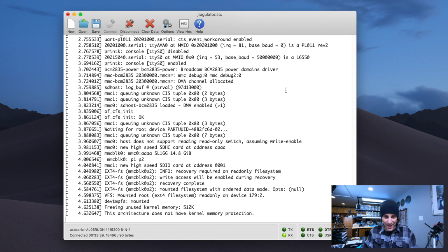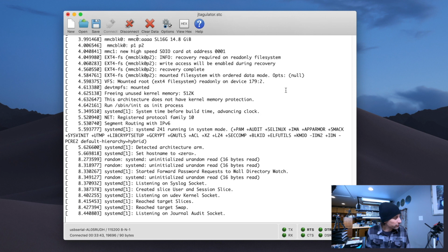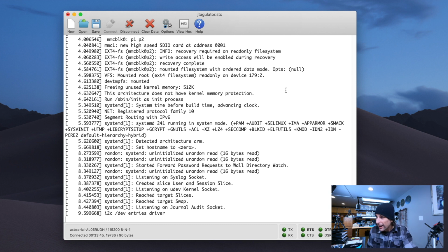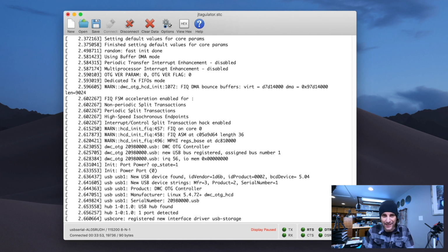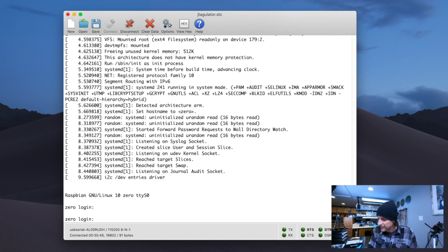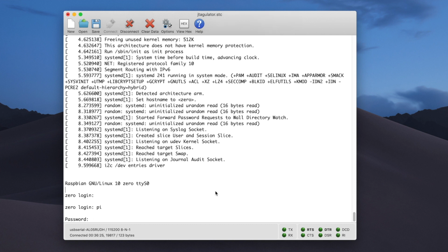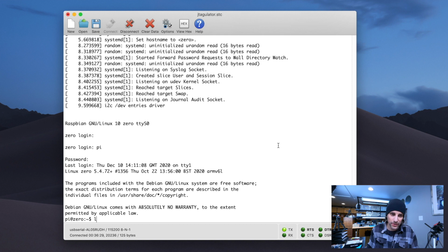Yes. Okay, so this is all UART data that's being sent from the Raspberry Pi to us over those pins that we just detected. And some of this data stream is what was detected during that TX scan. It's seeing these signals come by and saying, oh, I'm going to measure that. So we're going to log in here because that's going to let us show the next demonstration. So I'm going to log in as Pi. So now I'm logged in just to our normal shell.